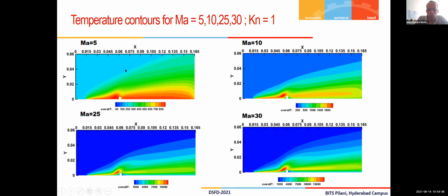And these are the temperature contours similarly, and we see that there are several phenomena that are causing this. First, right near the wall, there's a very high value of shear forces, which lead to a high value of viscous dissipation. So temperatures are very high here. And again, at the upstream edge of this step or cube, we have a stagnation point which leads to compressibility effects and therefore high temperature values. And the same trend is observed for all the Mach numbers. The only difference is again, the maximum peak temperature increases with Mach number.